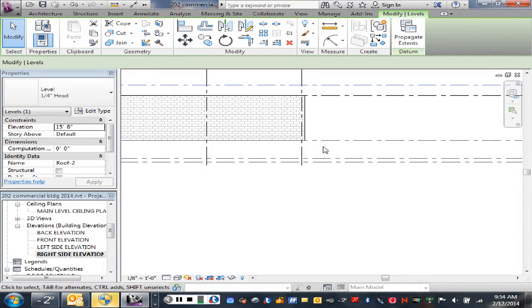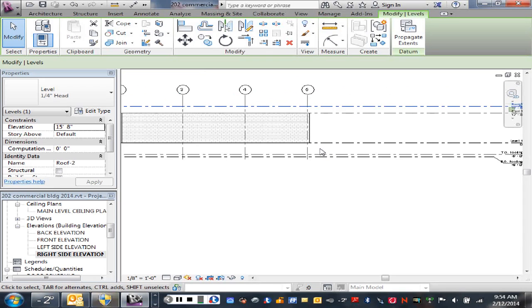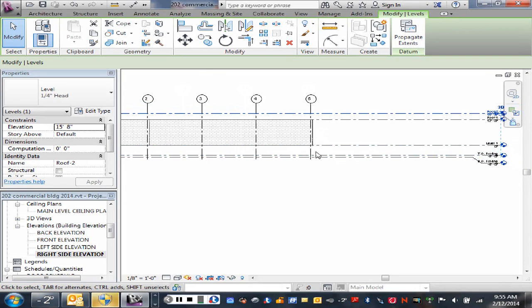So we're going to say that our precast concrete planks are going to be 8 inches in depth and thickness. Okay, with an 8-inch precast plank, we can span up to about 30 feet roughly. But again, we can look that up and find that information out. Precast concrete planks, you're going to be required to have a topping of concrete over top of that because the planks are irregular on top.